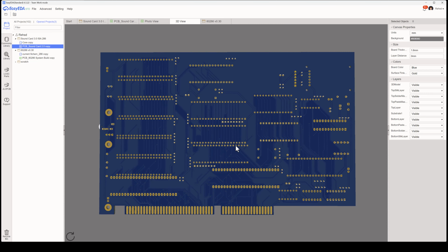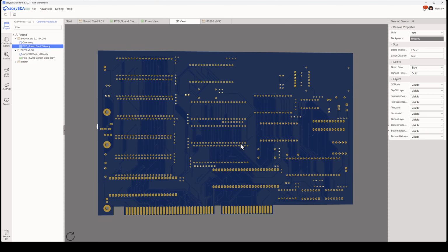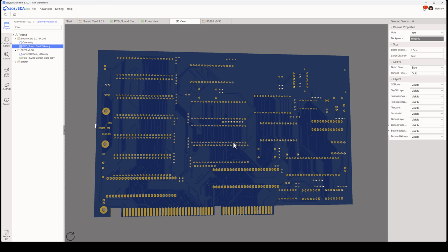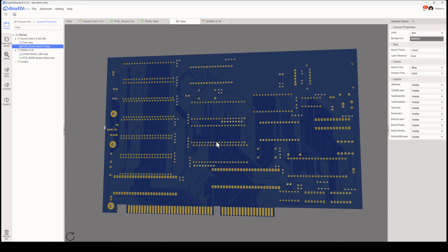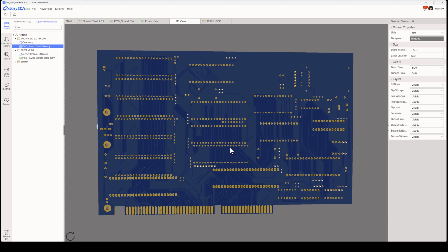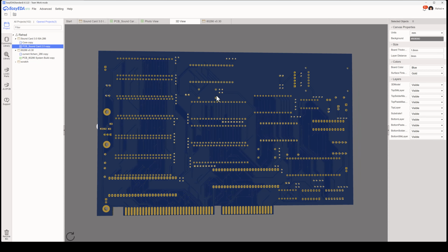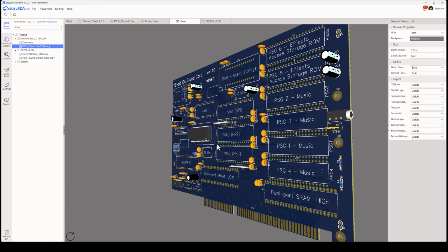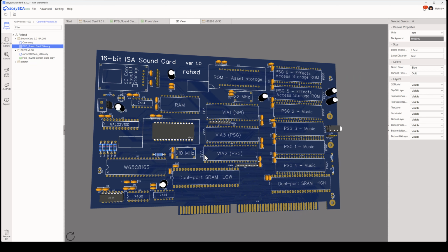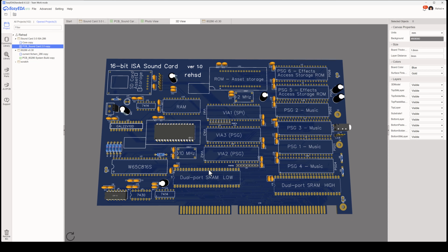I did go with a full millimeter for all power and ground. I went with a larger via for power and ground. And I can see that I've got pretty good coverage, I think, on the copper fill. So any of the copper fill on the bottom is ground. Any of the copper fill on the top is VCC. And the only area that it might be more thinned out is just down here, just because it's packed full of tracks. And you can see there's a lot of vias down in this. It just gets kind of messy.